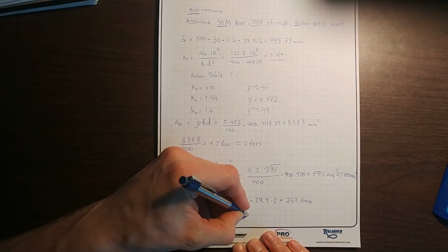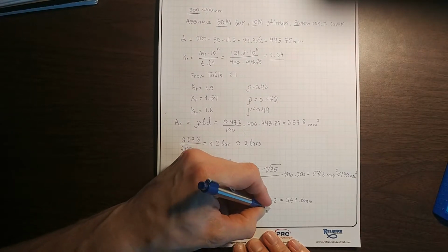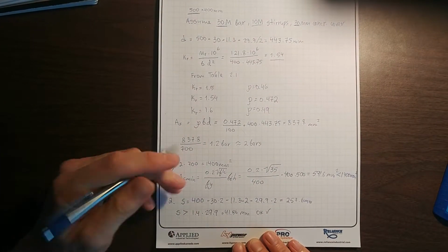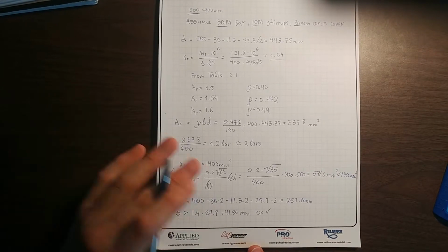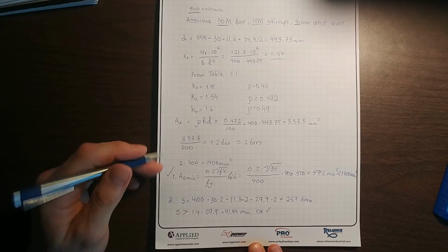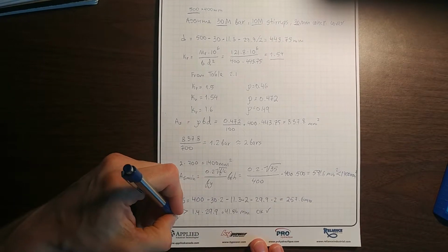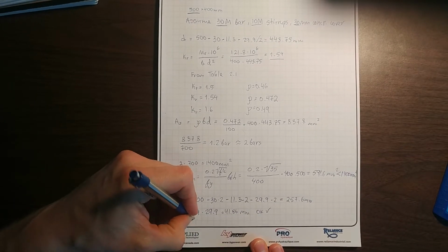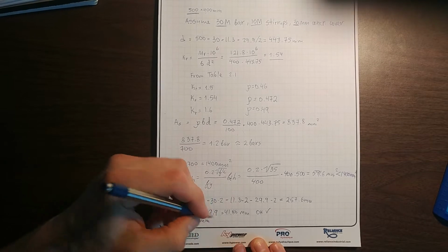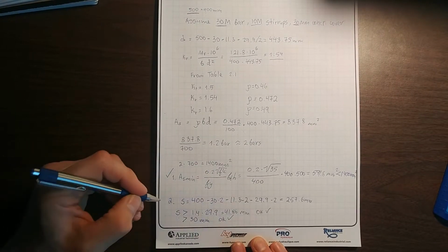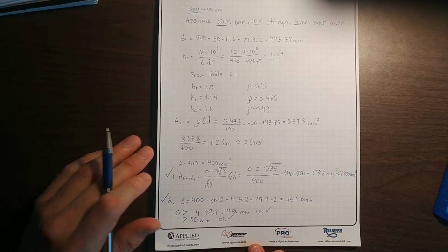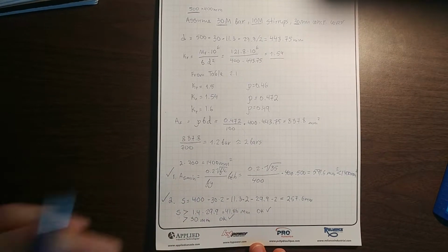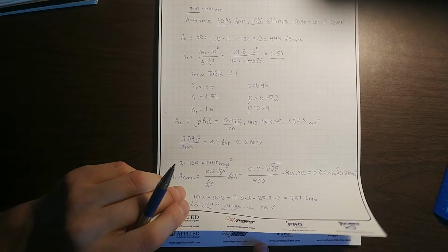We get 41.86 millimeters. So this is okay. Since the problem doesn't tell us the aggregate size, we just ignore it and don't count it. And then also 30 millimeters. Since the spacing is bigger than both of them, this check is done. It's all good. So the last check for this beam is called the crack control, and